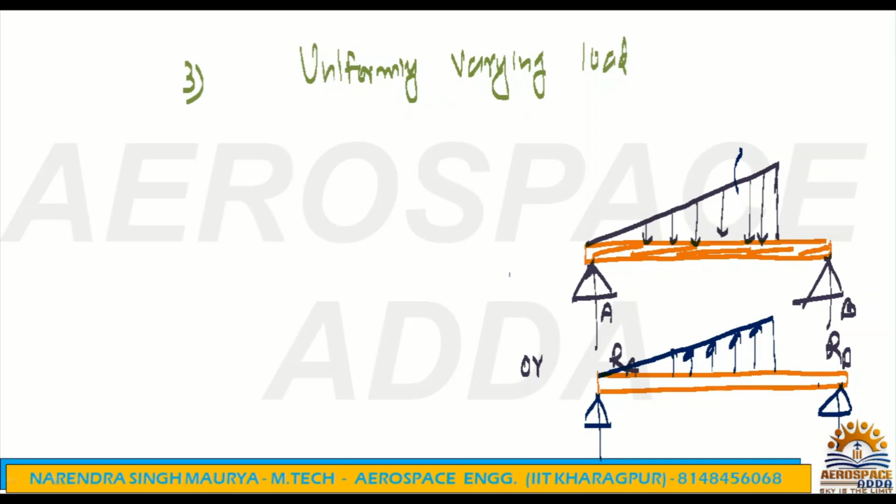UDL throughout the span will be constant, it is not going to vary, but for UVL it is going to vary. For example, I will show you: at this point, what is the value of UVL? It will be 0. Continuously it is increasing, so just say 1, 2, the magnitude is continuously increasing. Check 5, 6, 7, like that it is increasing or not. See the magnitude of the length of this arrow, you can understand this is the measurement of how that uniformly varying load is increasing, that's the meaning of it.